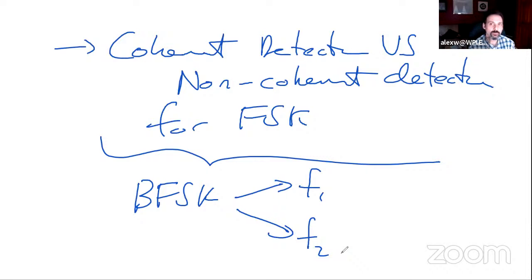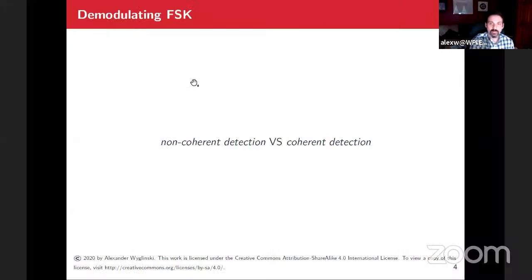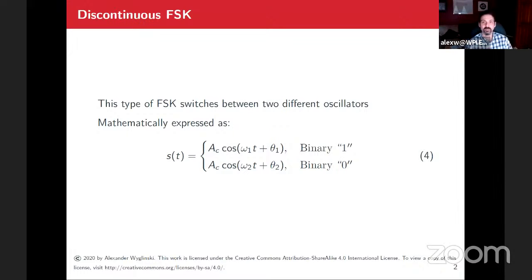You should be able to see how you go from one frequency to another in a seamless transition, without any abrupt changes between two different symbols at the symbol period boundary, right? That is a major takeaway from this lecture. You should also be aware that there are two different types of FSK. It's not just that FSK is FSK. There's a graceful way, and there's a more abrupt way of doing it. And of course, the spectrum looks rather complicated.